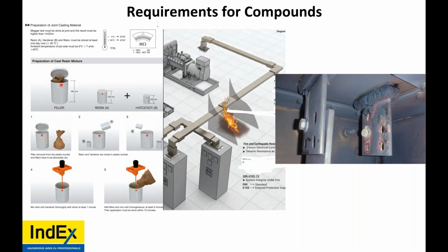Bus bars don't provide the same flexibility of cables. You have to be exact with bus bars. With flexibility, we mean flexibility in where it can be used. We don't mean the actual flexibility of a cable. Flexibility as in you don't have to worry about breaks in a cable, insulation resistance, how many cables you need, weight considerations. The weight of that bus duct, the amount of amps it is putting through, would require significantly more cables over a bigger space and significantly more weight.